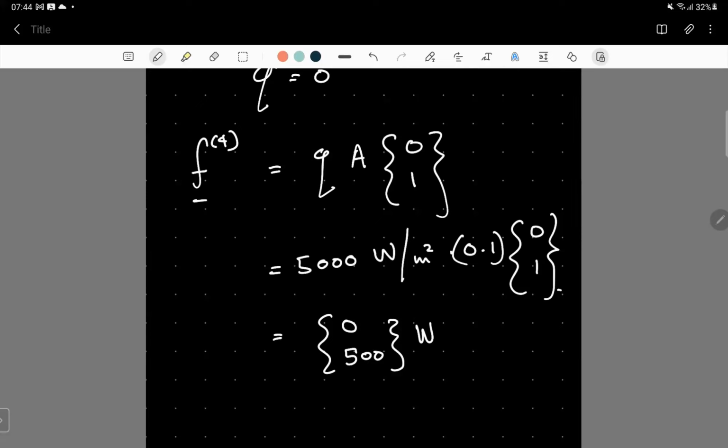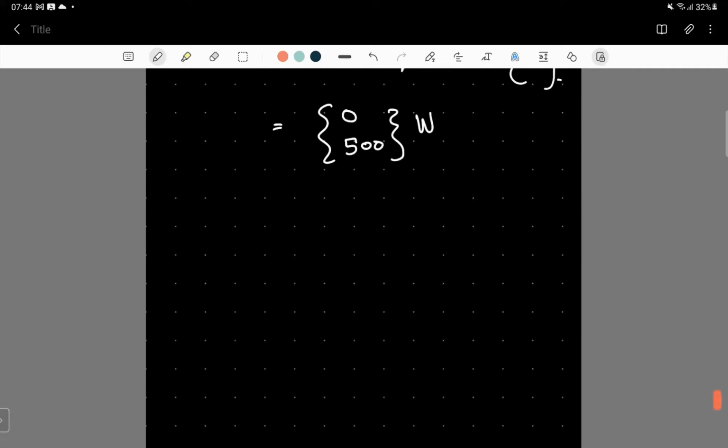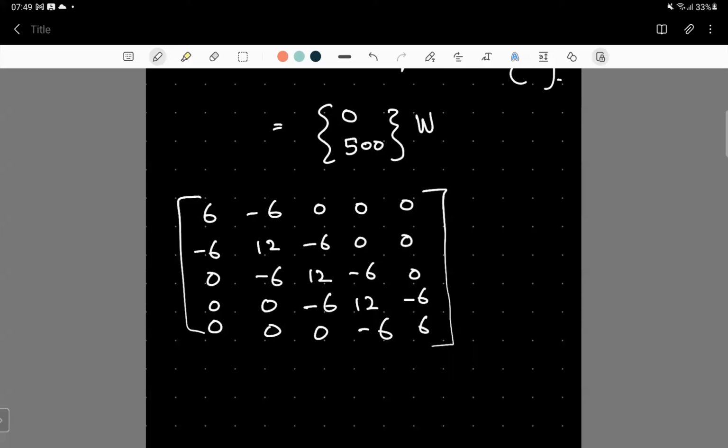So now we have the stiffness matrices for each element, and of course we have the corresponding force matrices. Then it's the same protocol again. You assemble the global stiffness matrix and the global force matrix. We obtain the global equations like this. If you use the direct stiffness method, of course, you would get this. All right. So by assembling, we get a symmetric equation.